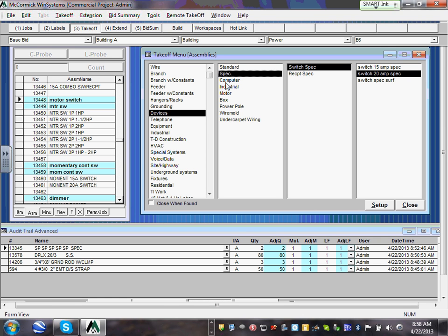What I've seen, sometimes when you have the boxes with the light, they'll use that plastic, it's like the flex. Fixture whip, you can assign a fixture whip to a fixture, or if you're using fixture whip, guys, the code says it can't be more than 6 feet. After 6 feet, you have to support it. But if you put your boxes and conduits close enough within 6 feet of every fixture, then you just take a fixture whip and tie it to these boxes and group them as they move on.